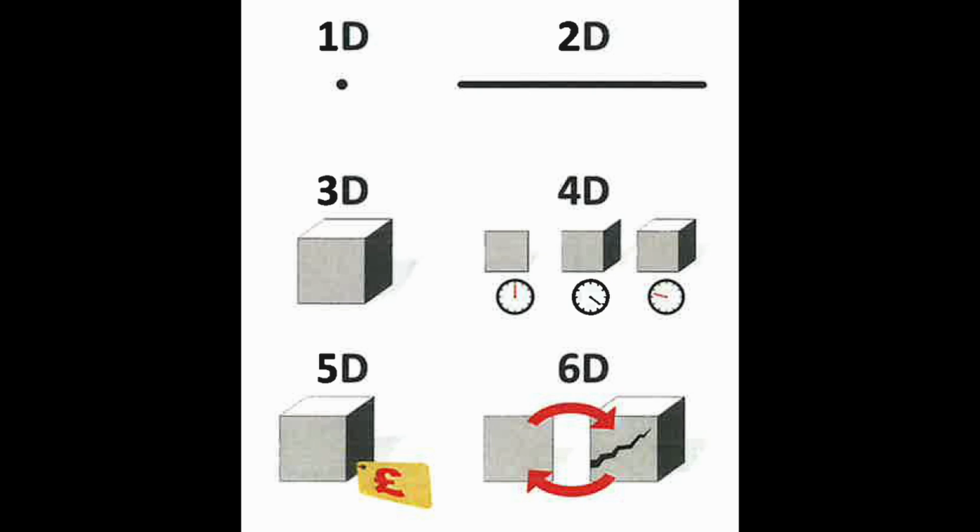Model use across project lifecycle. One of the strengths of BIM is that the same model data can serve multiple stakeholders: architects, engineers, quantity surveyors, contractors, and eventually facilities managers. However, each of these uses places different demands on how the model is constructed. A concept architect's model is fundamentally different from an FM handover model, and trying to satisfy all possible future uses from day one is neither practical nor cost-effective. Revit supports a far better approach, allowing components to be swapped and enriched with metadata as project requirements evolve.